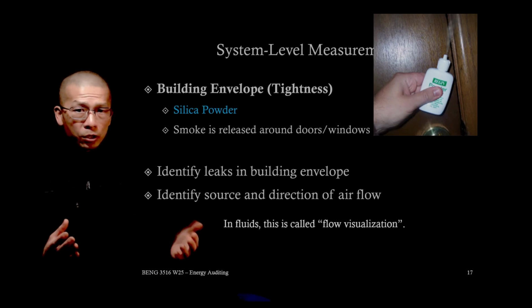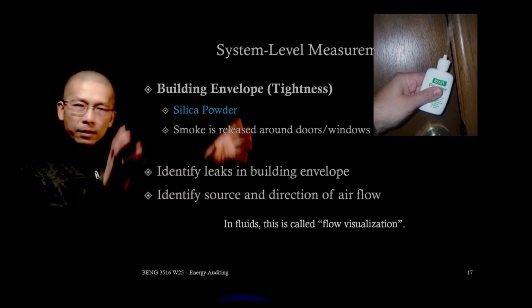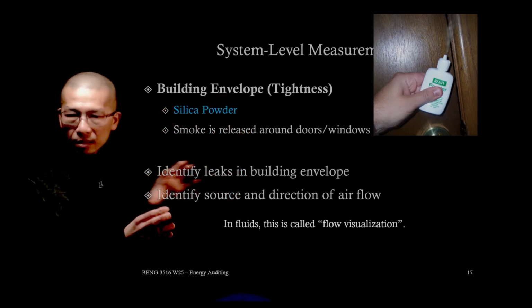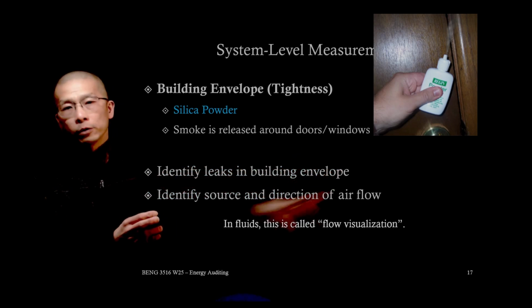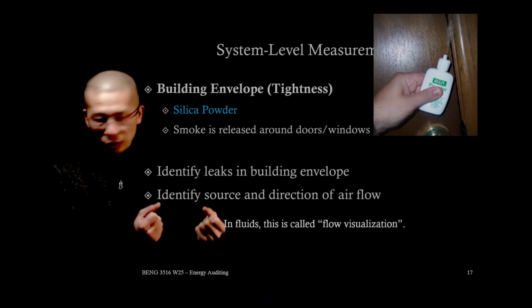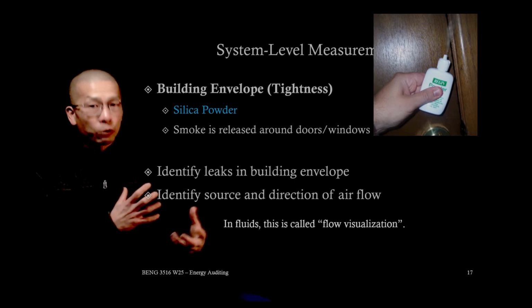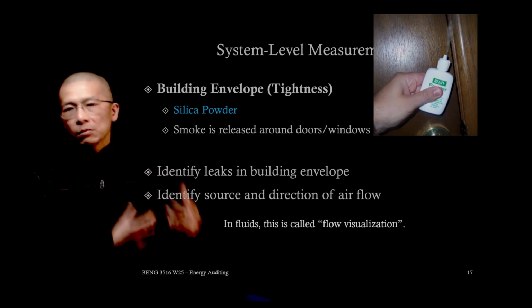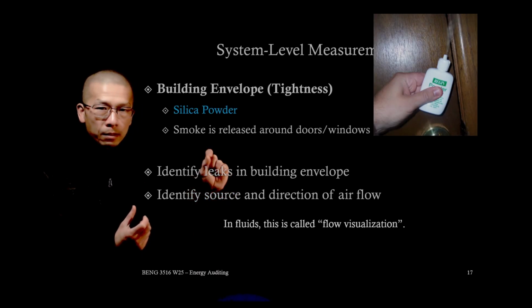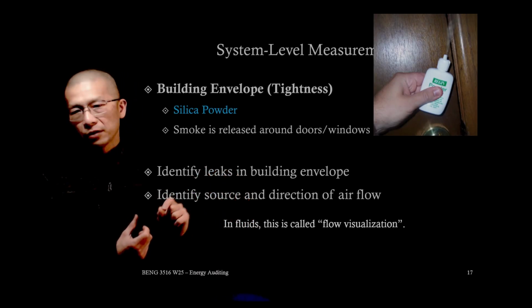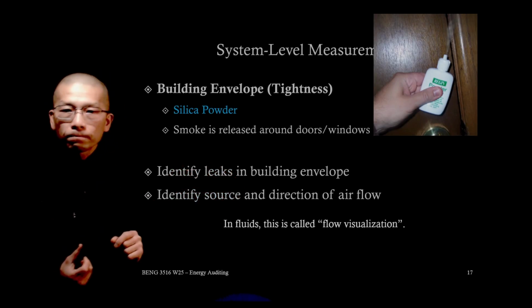They vary. So what's called a blower door test, we blow air out from indoor to outdoor, which creates a kind of suction, and therefore there's a pressure difference between indoor and outdoor, right? That's the driving force. Okay, so that's a repeatable pressure difference that we can create to do that kind of test.